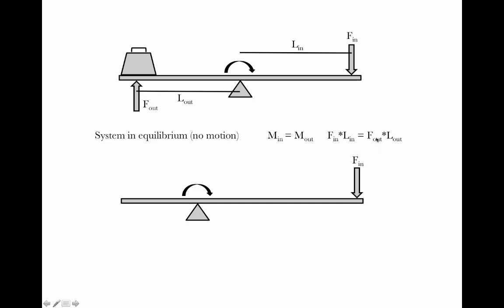So it's going to get as much force output out as it put in in this system with equal leverage. Now what we've done is we've made the leverage unequal on the two sides of the fulcrum. Let's say we have the same input force and we want to see how much weight we can balance on the other side. So now we've got a much longer in lever than out lever. We've doubled the size of the in lever relative to the out lever.